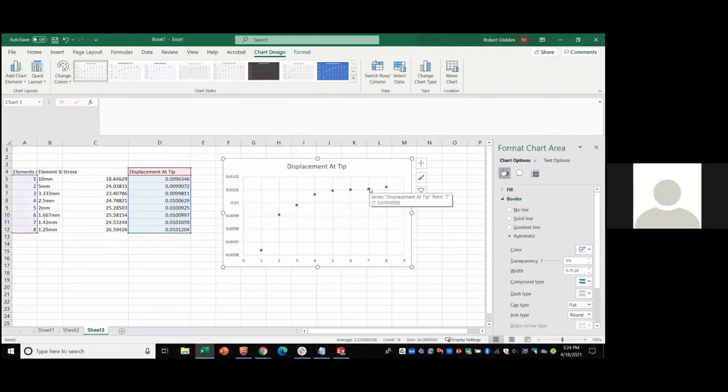And when you have a solid finite element, the computer doesn't really consider bending of a solid element very well. So if you've only got one element through the thickness, it can't consider tension on one side of that element and compression on the other side as accurately as if you've got elements that are experiencing specifically tension and elements that are experiencing specifically compression.